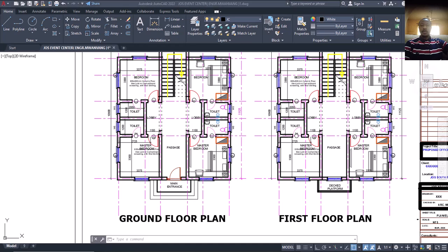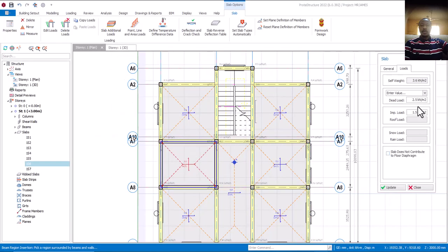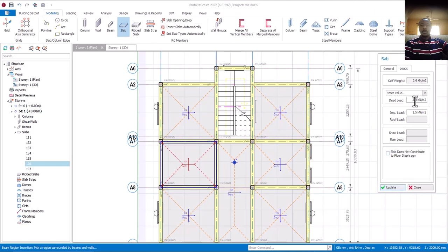So this place is going to be resting on top of this slab here. That is why coming to this place now, I'm going to load this 2.5. I'll now click on update to update it. And once you have done this on 2.5, then your own detailing should have a rebar spacing of 150, even though it's passing at 200. You make it 150 spacing.